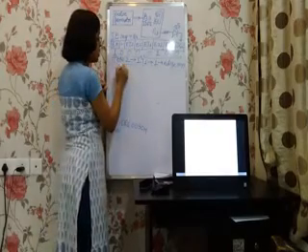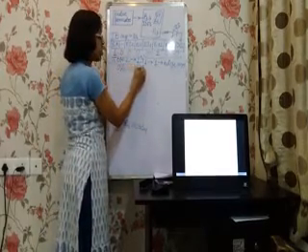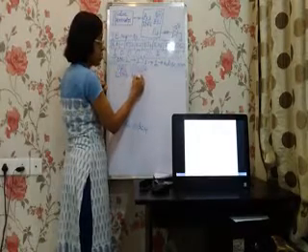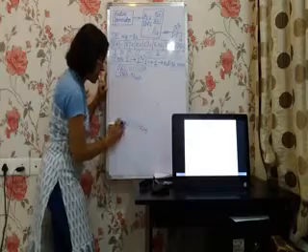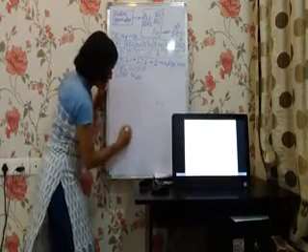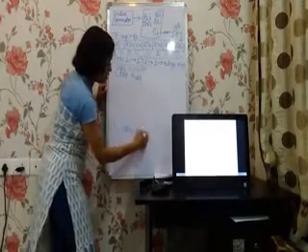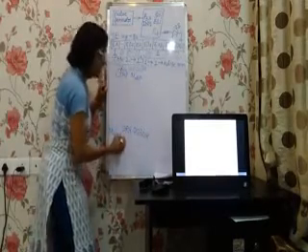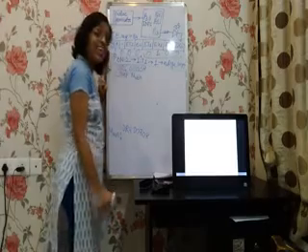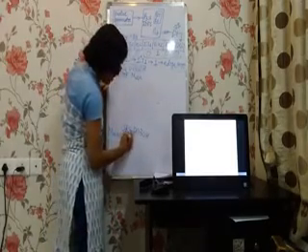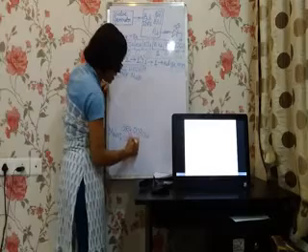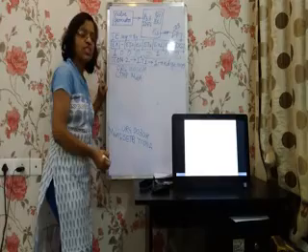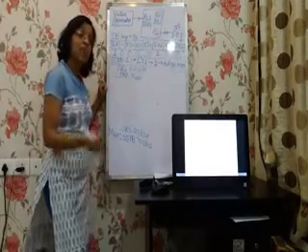So I give an ORG again here: ORG 0000H and an LJMP main. What do I do in the main program? I start my main program from ORG 0030H. I first define INT1 as an edge triggered interrupt. So I give SETB TCON.2. What will this do? This will define INT1 as edge triggered.